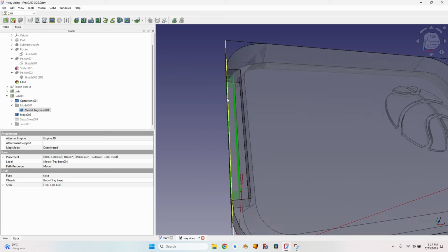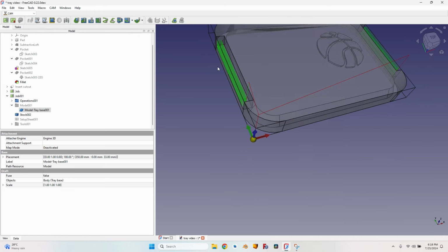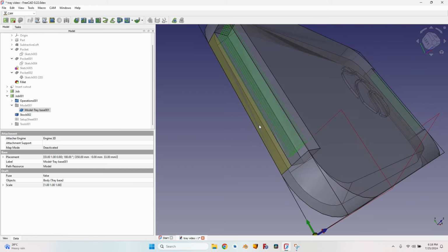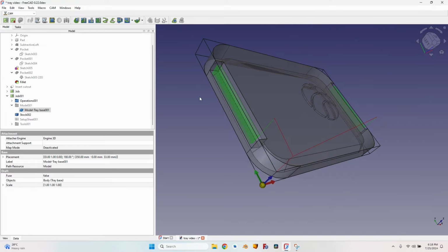Even though the shape looks square, here you have to take into account the shape of the cutter head, which is a bullnose cutter head. It will leave a very nice roundover for all these edges, so the handles will look very nice in the end, even though now you have to rely on this hack to reduce the radius for the corner in order for this to work.